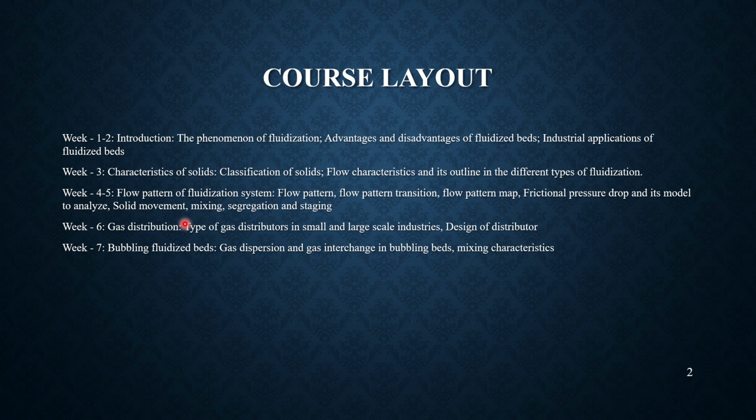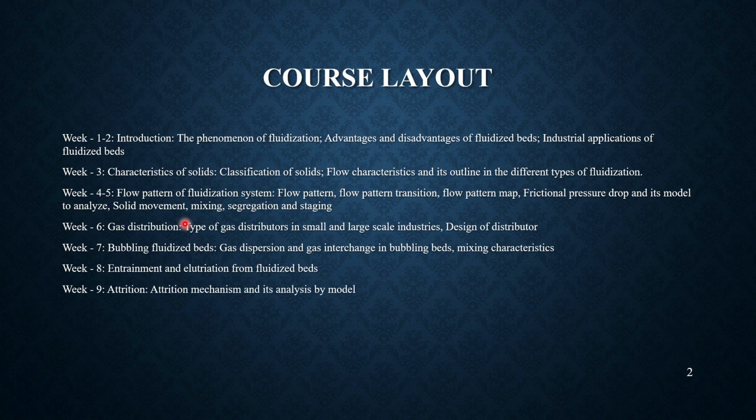And staging is nothing but when we are collecting the solid particles at each interval of time, not each interval in the bed. So a certain group of particles with a certain density range should be collected. So staging is used for that purpose. And week 8 it was about entrainment and elutriation from fluidized bed, which is nothing but the carryover of solids, mostly finer size particles, away from the bed, which is known as entrainment. And if we are dealing with collecting a certain density range of particles, it is known as elutriation.